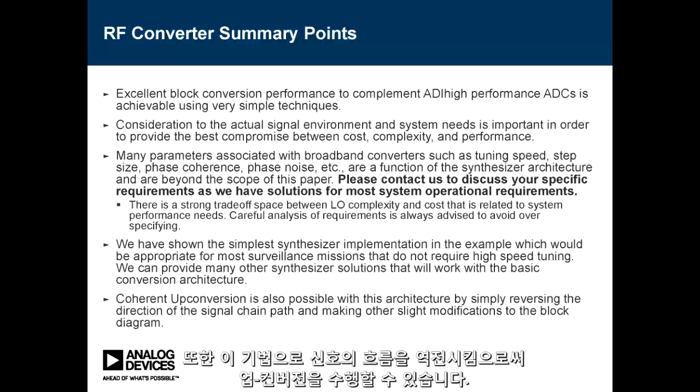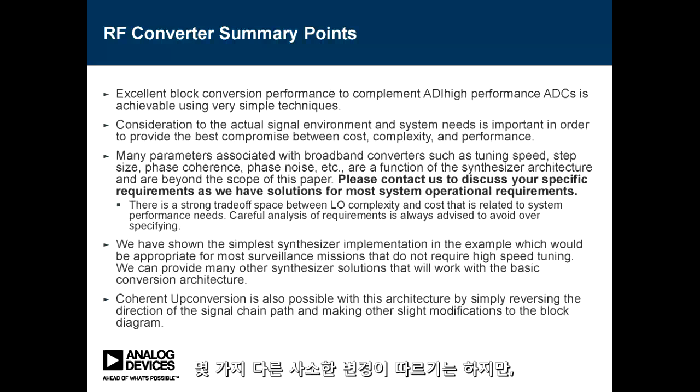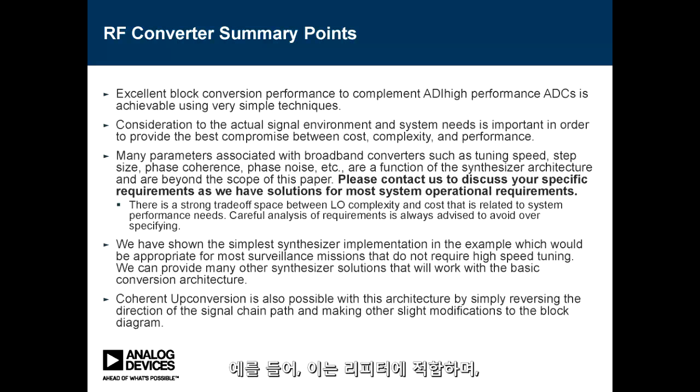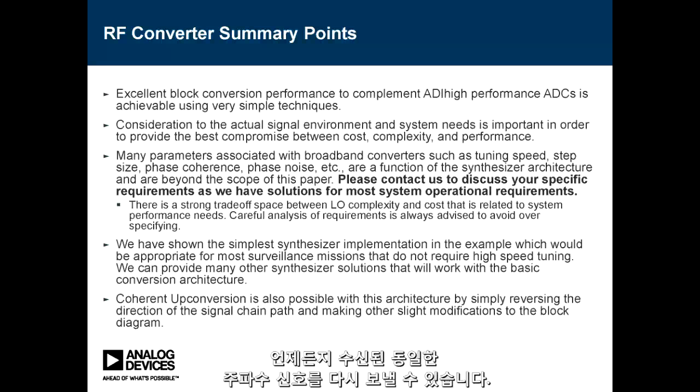Also, you can do upconversion with this technique just by reversing the flow of the signals. You have to make a couple other minor changes, but basically you can use the same thing for upconversion and downconversion using the same LO, which is good for repeaters, for example, or anytime you want to send back the same frequency signal that you received.